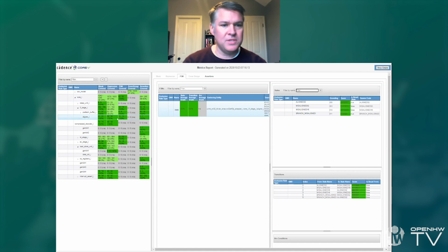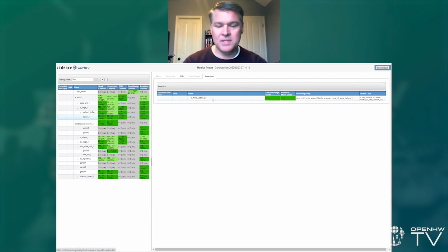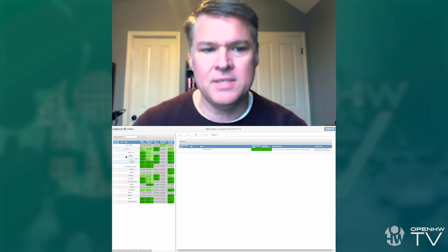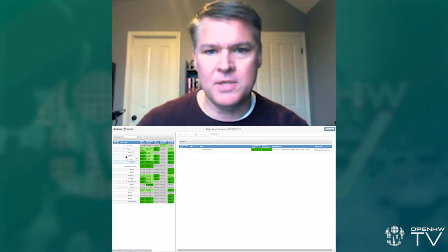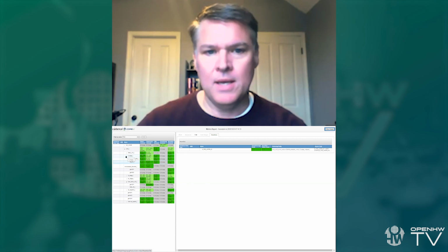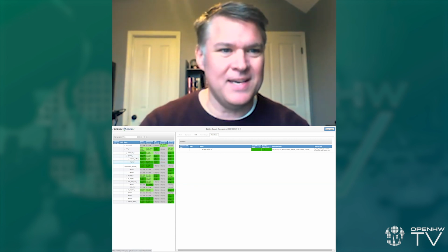Going into the assertion coverage, if I could skip around just a little bit, we've written quite a few assertions internal to the design. And by clicking over to the assertions, you can get, again, an idea of what those assertions are. And if there are any that are missing at this time, we're really close. So we're getting very close to having all of our assertions. And this also covers cover properties. So if there are any low-level signal conditions, especially on external interfaces, interrupts are a very good example that you'll find in this report, where we've self-defined a lot of coverage from our verification plans, you can get proof we've hit all those by clicking down there.